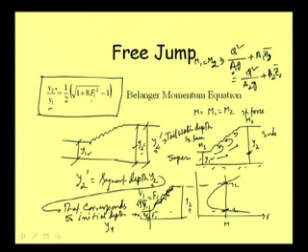So, this way we can find out this area and z value, and then we can calculate this m1. Then we need to calculate the y2 value by trial and error procedure in such a way that this y2 will give us a value of specific force equal to the specific force that we have already calculated with the depth y1. And one point we should remember, y1 is less than critical depth, and y2 will be greater than critical depth. So, this part we need to know.